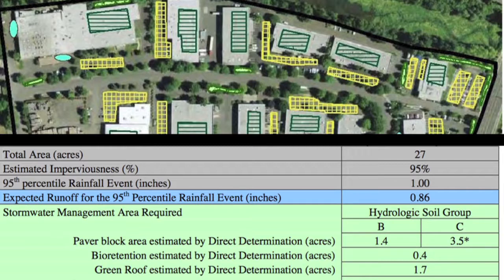Given these site conditions, there is not enough pervious area to manage the entire runoff volume discharged by the 95th percentile rainfall event with bioretention alone. As a result, other practices were evaluated and selected. The practices integrated into the design included a vegetated roof, cisterns, and porous pavement. Based on the technical considerations of constructing and maintaining control measures at the site, it was assumed that approximately 30% of the available pervious area could be converted into bioretention cells.